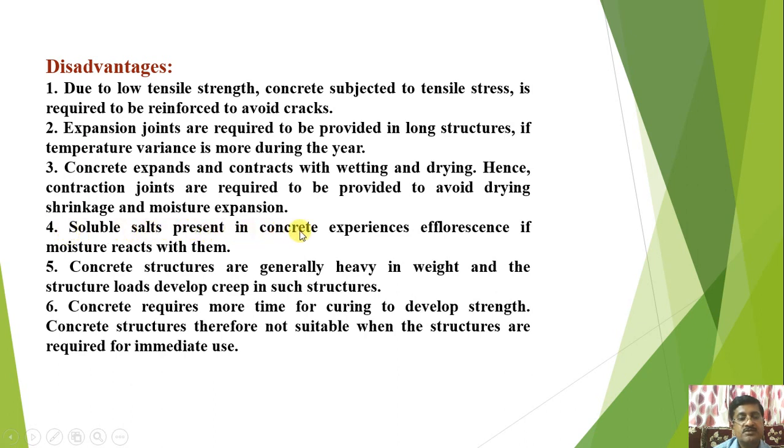Soluble salts present in the concrete experience efflorescence if moisture reacts with them. Concrete structures are generally heavy in weight, and the structure loads develop creep in such structures. Concrete requires more time for curing to develop strength. Concrete structures are therefore not suitable when the structures are required for immediate use.